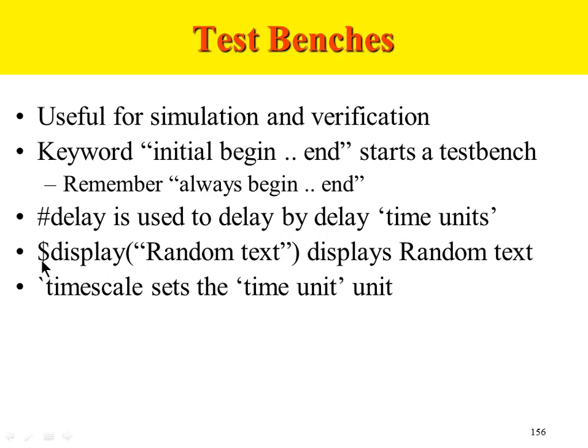Anything with a dollar sign is basically a system task. A system task is used for simulation purposes. Since we are going to use test benches for simulation, any system task can be used. Tick timescale will define the time scale. So the first thing that you do in a test bench is define a time scale. Because I'm going to be simulating my test bench, for simulation the time scale is critical. So we have to declare a time scale for the test bench and for the entire design.